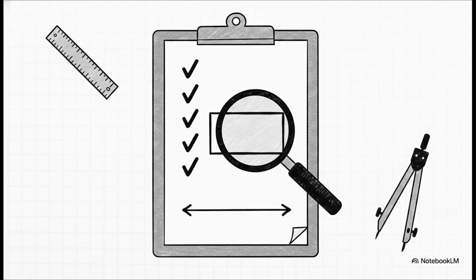To actually enforce this religious scrutiny, there's a ridiculously strict checklist that has to be followed before the actual track drawing even begins. Just look at these requirements. The title block size must be exactly 170 millimeters by 65 millimeters. The spelling of station names must be totally exact, pegged to a precise kilometer and chainage marker that shows exactly where the center line of the station building sits. Every single line has to have a clear designation for up and down traffic. Oh, and you must map out the nearest junctions and block section lengths. It is a rigid, bureaucratic grammar designed to ensure absolute clarity. Because out here, a typo doesn't just mean a quick eraser correction. It could literally mean a collision.